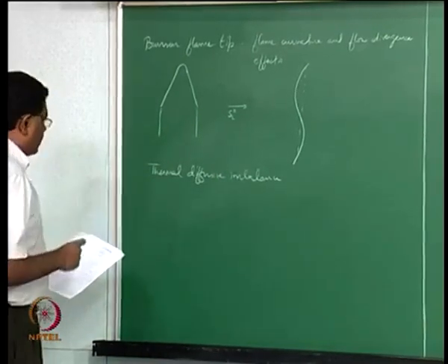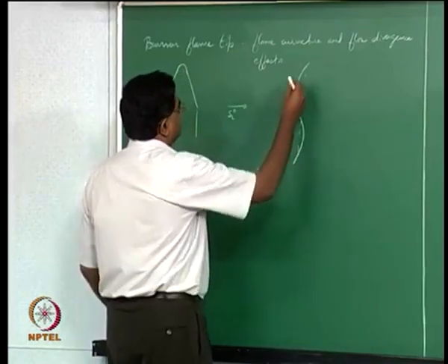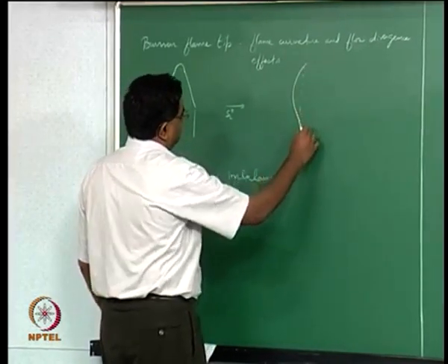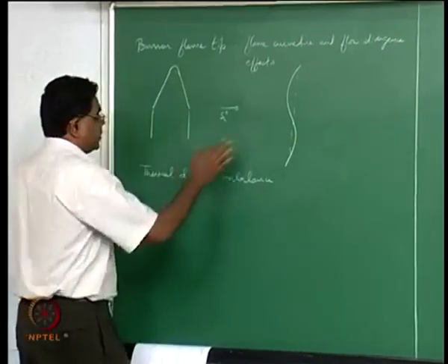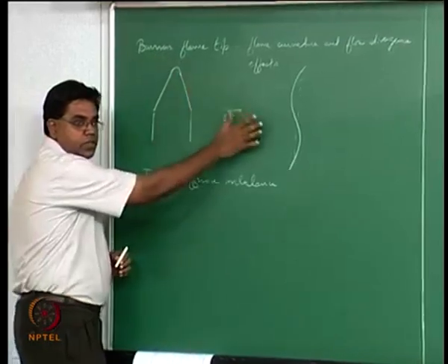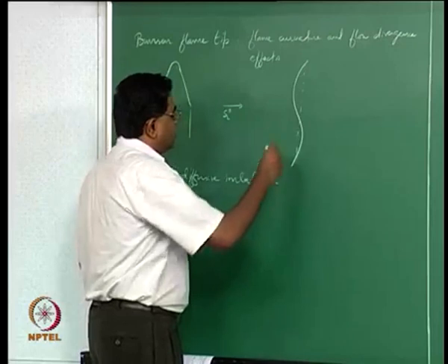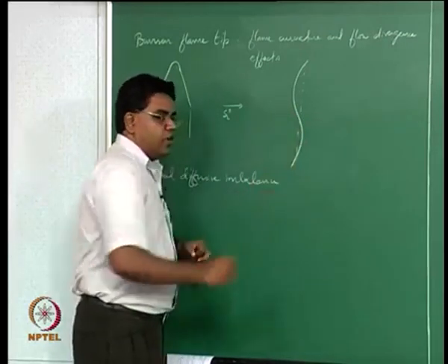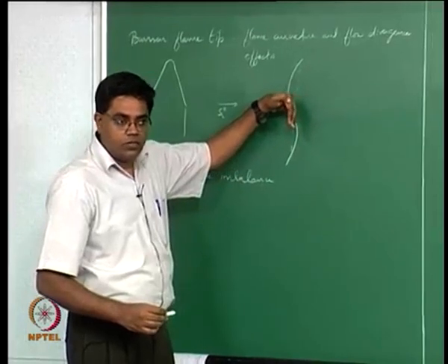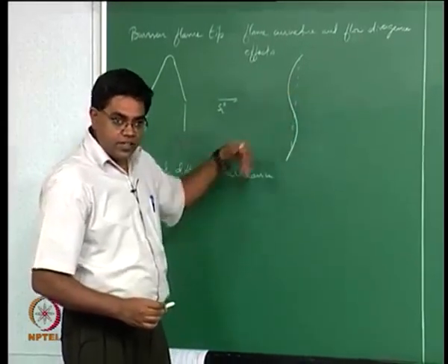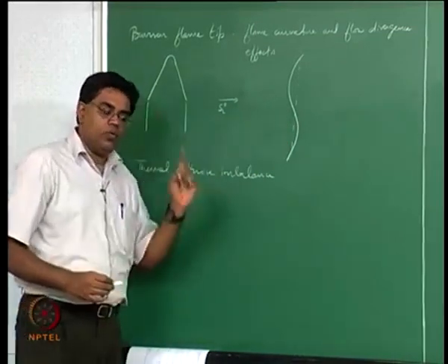So one of the things that happens is when you have a flame that is curved, let's take the concave part. This is a little bit more intuitive, and it's also what's happening in the Bunsen flame tip, so this is pretty instructive. When you're thinking about a curvature which is of the order of, not exactly equal to, but still a little greater than the flame thickness, keep in mind what is meant by flame thickness.